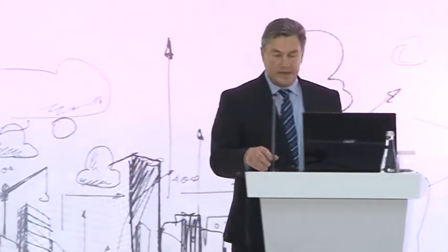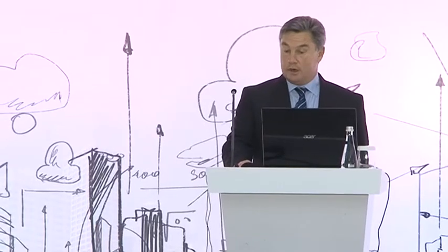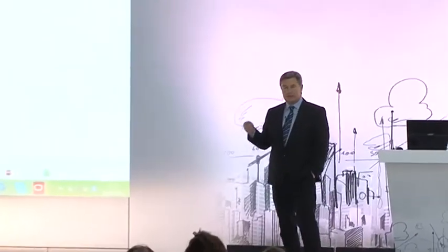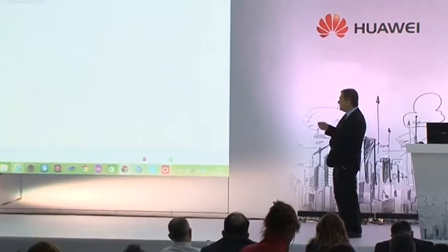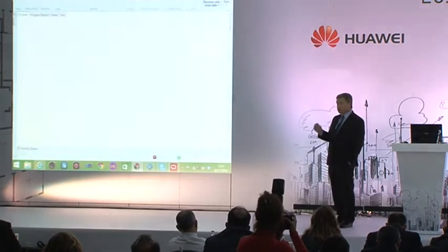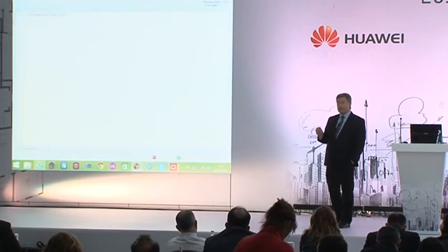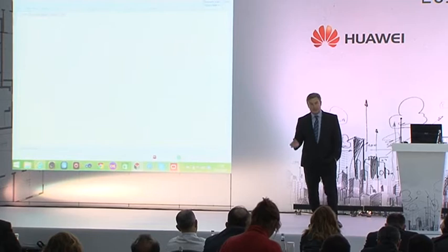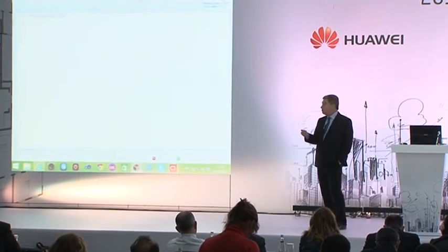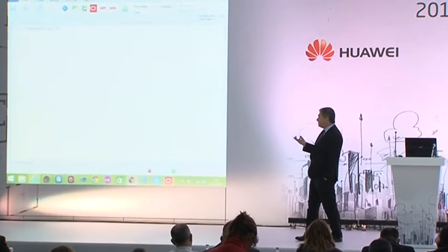So we can import data from P6, which is the one I'm going to show you today, in a variety of formats. So we can go direct to the database via the SDK or import XER files or XML files. And one of the beauties of that is it means that you don't have to have Primavera on your machine. So it could be sent, if you're a client, for example, it could be sent to you and you could run your own S-curves. And it's extremely simple to do.